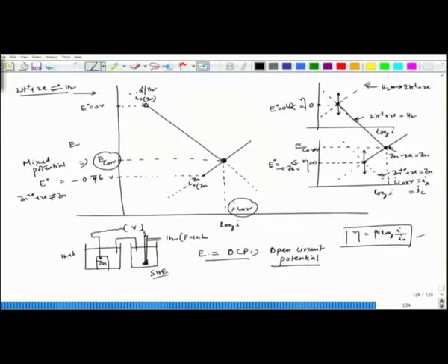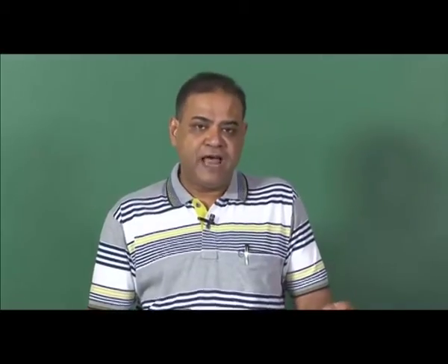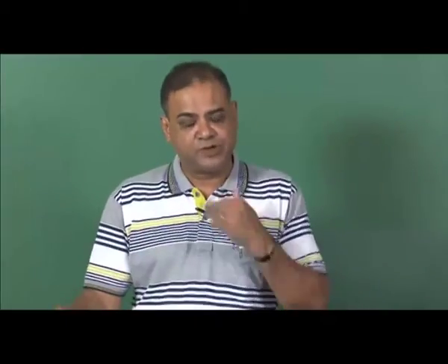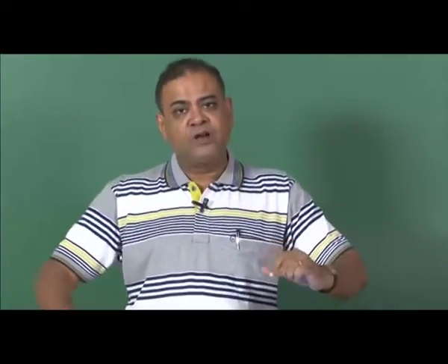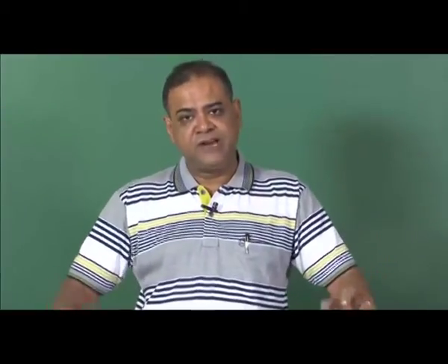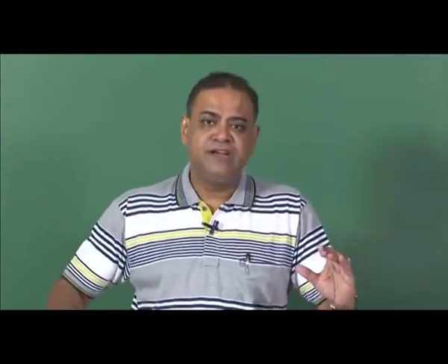See, this open circuit potential is the new point from where we have to consider the polarization during experimentation. That is what we do in the lab in a polarization experiment: we try to achieve the stable open circuit potential, and that one is considered as the new zero overvoltage. Then we try to go to the positive or negative side and see what my net current flow, or I applied, is.